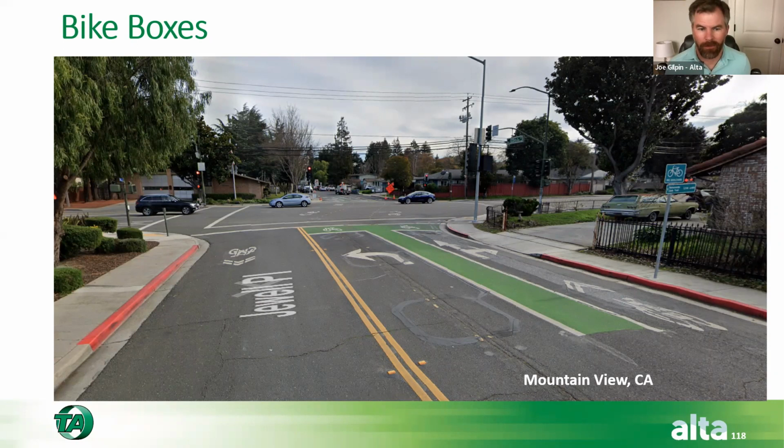So downhill approaches are not good, but bike boxes can be good for treating right collisions, but there are other things that we can do too. I think the setback crossing has a much better potential to address right hook collisions. Another thing they're really good for is if you have a lot of bikes.